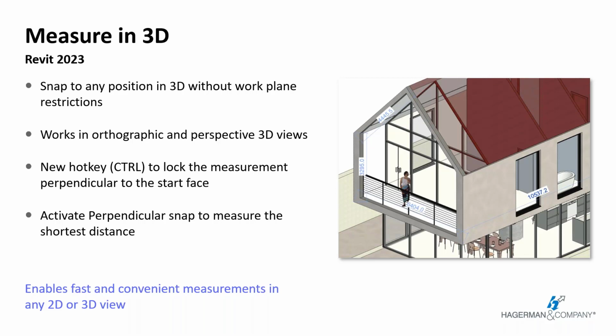With a new hotkey, the control key, you can lock the measurements so that it remains perpendicular to the start face in 3D views. This might be useful when measuring the distance between two walls. I've had a chance to play around with this.